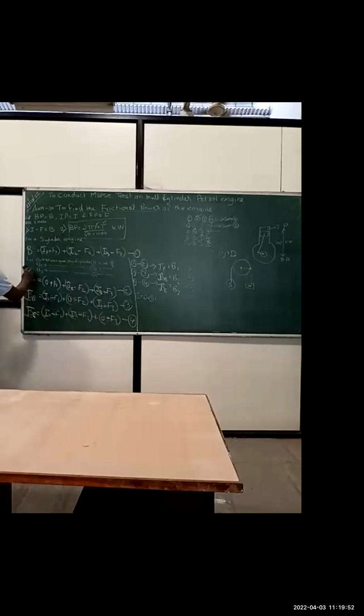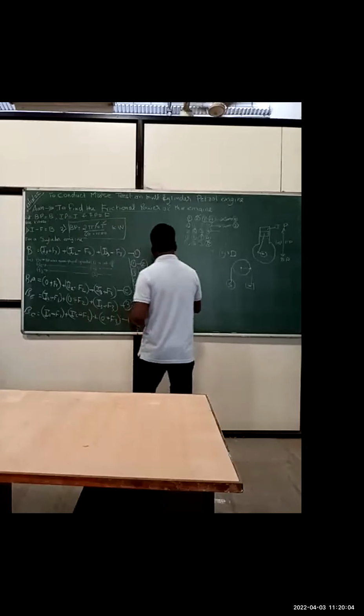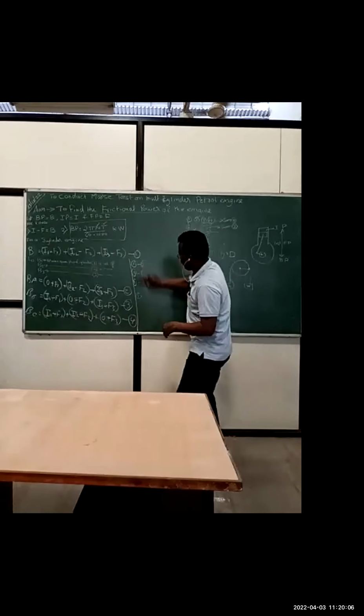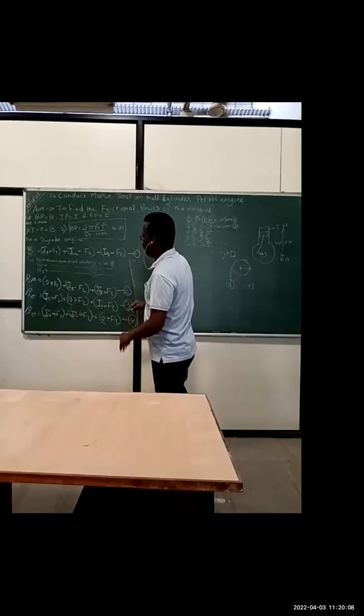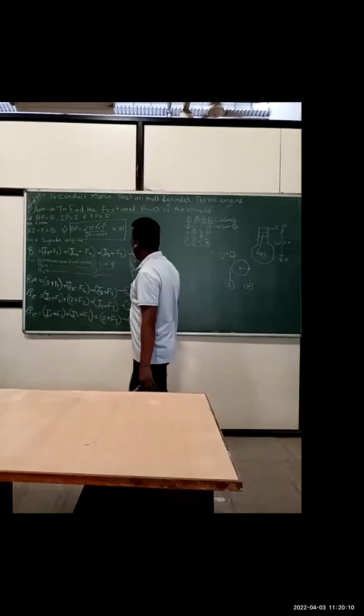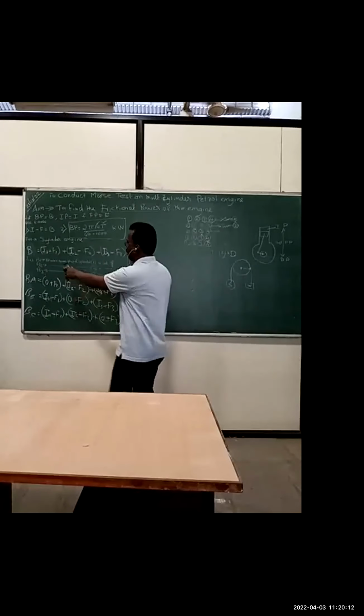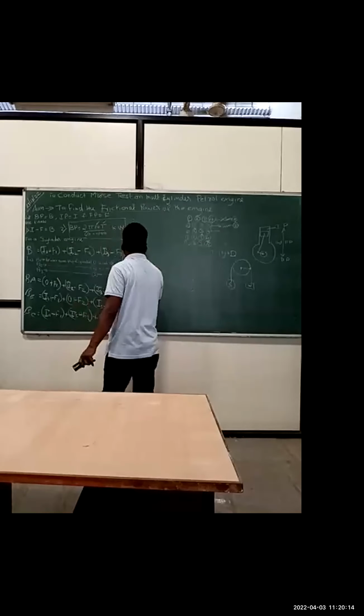And as usual, here it will be BA, let us say BB and BC. Okay, doesn't matter. So now B minus BA, 1 minus 2 will give you the brake power of the engine when number one cylinder is cut off.